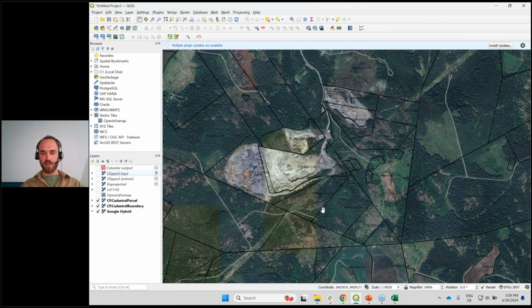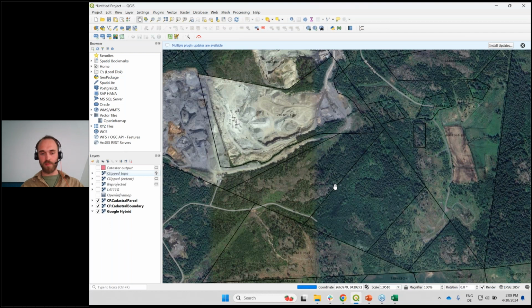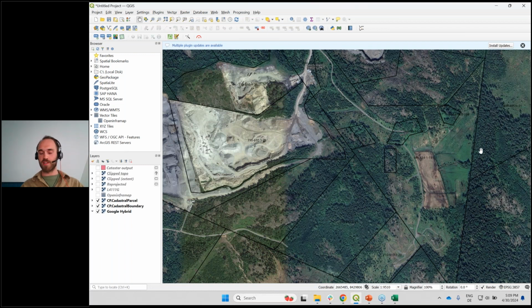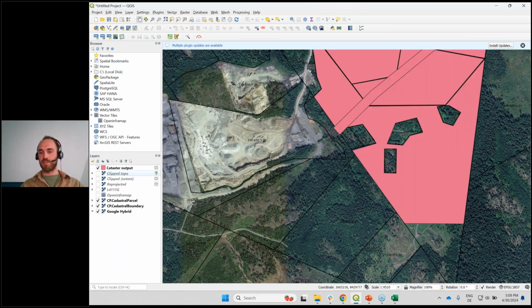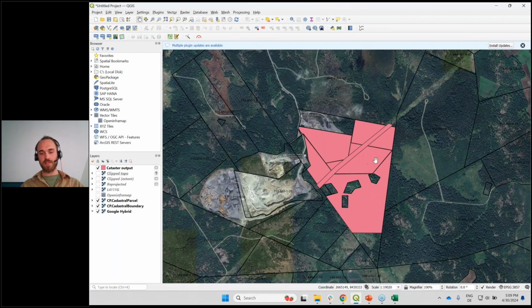If I zoom in here, I can see the exact boundary layers of my cadastre data. So I would know exactly where my PV plant area should end and where a new area starts. So in the next step, with this information ready, which is already increasing my accuracy, I made this selection here. I had polygons selected. I chose these 4 elements here, and they are basically the cadastre data I was interested in.